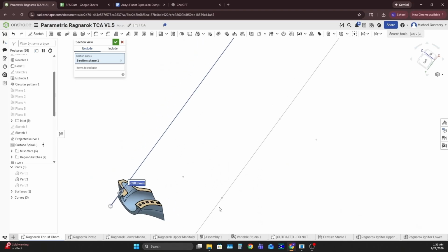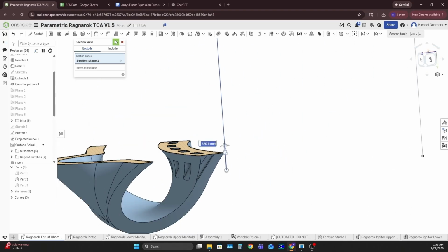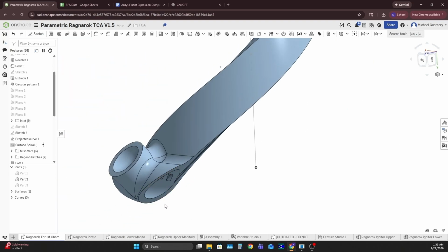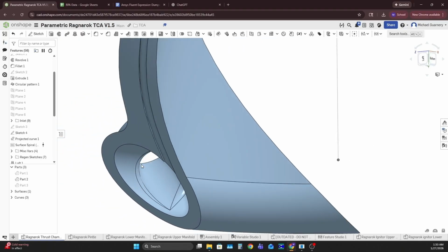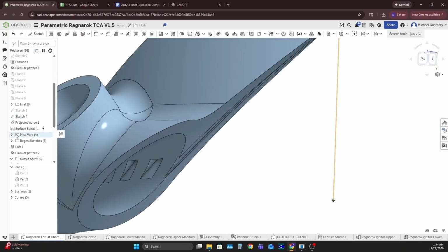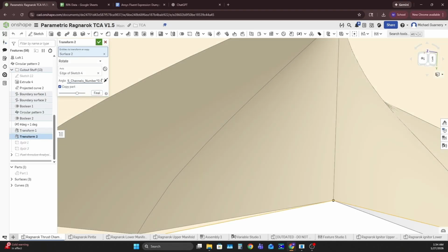The other thing that we want to watch out for is we don't want this piece right here to be showing down here, because it'll make our volume extract feature difficult to use. So we're going to have to go back in here. We're going to go transform 2, and then we can edit the last part of this, and we can make this like 0.2.